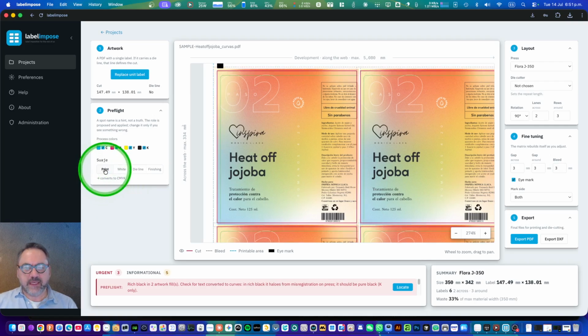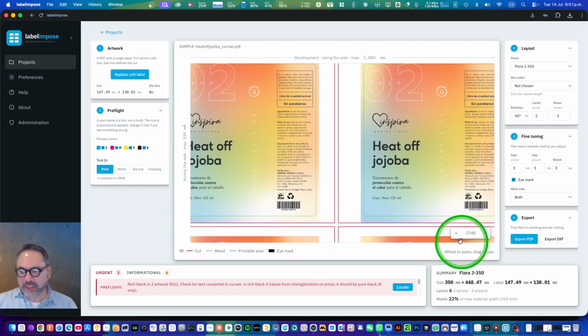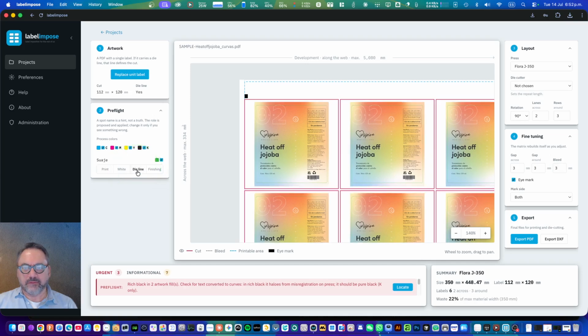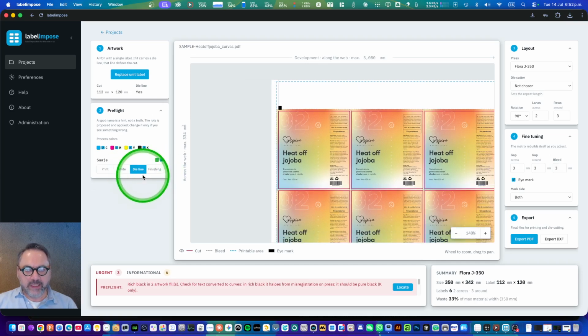And in case we decide it will print, it changes everything. It changes the geometry of the imposition, because now the system doesn't know where to start calculating the bleed area. So everything in our process is related to the die line, just as label production is. So we get back to this: this is the die line, and everything changes.